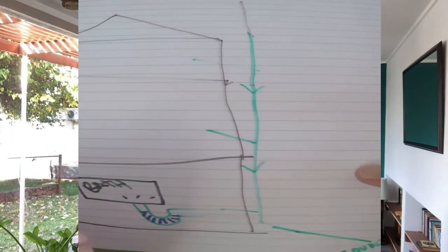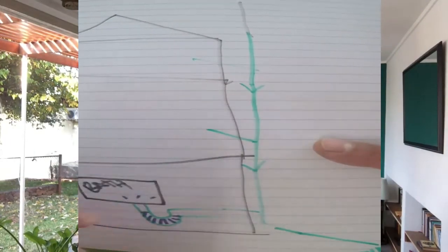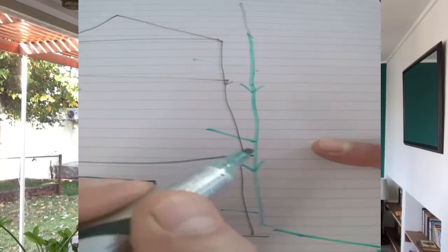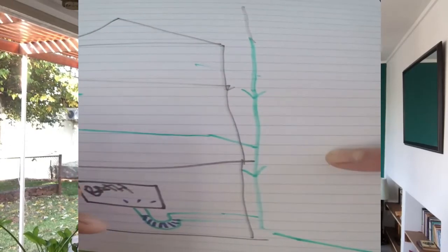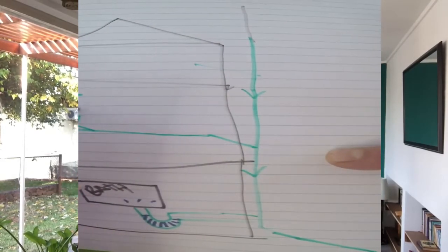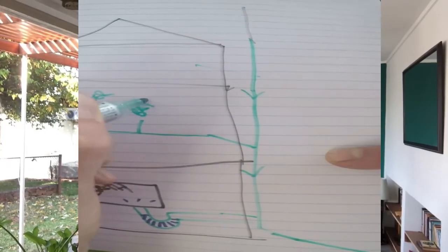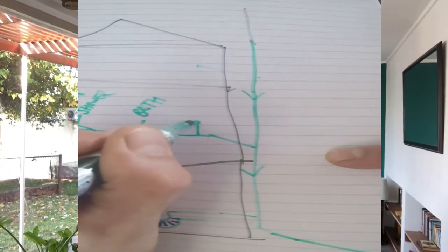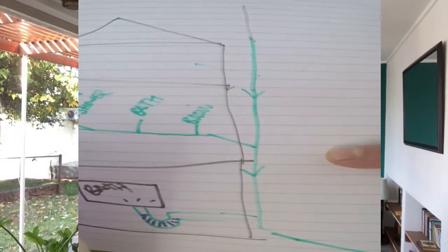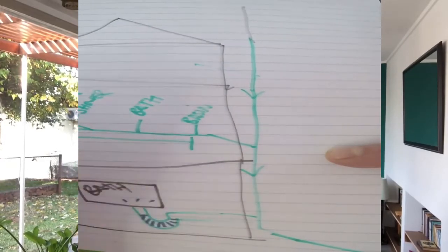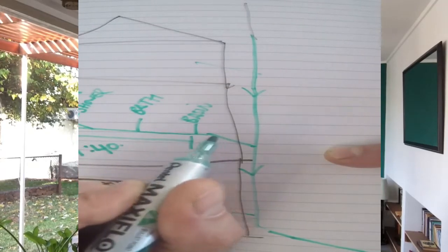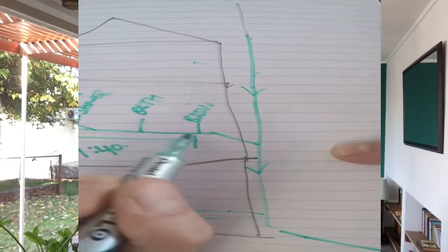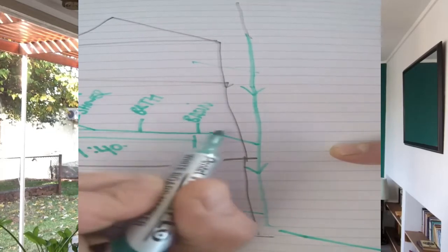So if I'm running a bathroom, or let's say the first floor here, and this is my main pipe, and I want to go and pick up a shower, I want to pick up a bath and a basin. This pipe has to drop 1 in 40, and as it drops, I have to make sure that my gradient falls enough for the water to go down.